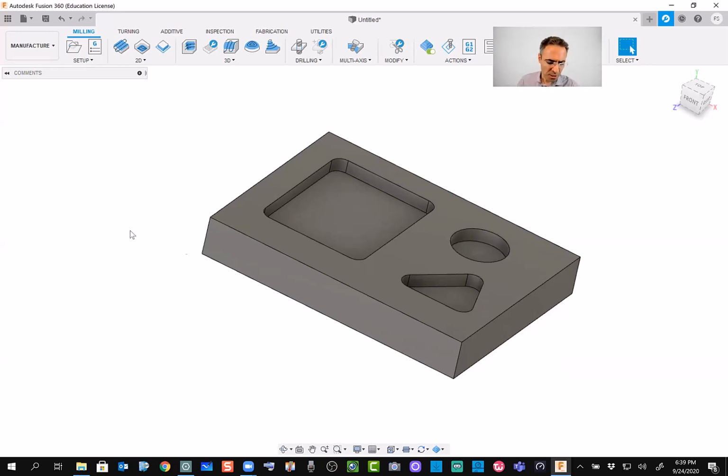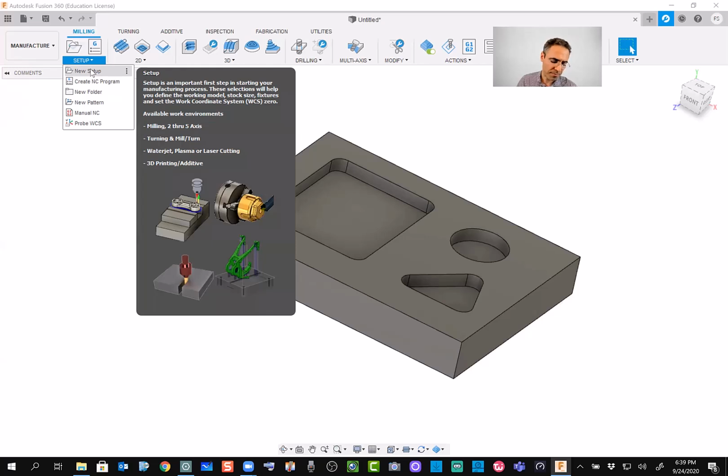Okay. So what I'm trying to say, nowadays we just create a G code and do the automatic milling rather than doing it manually. So we are here, 2 simple steps to create a G code. How do we do that? First step, always setup. Over here, you see the first tab that I have here, setup. I open this one, and I say it's a new setup.